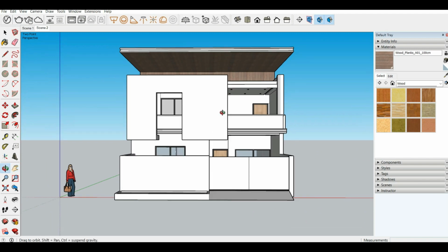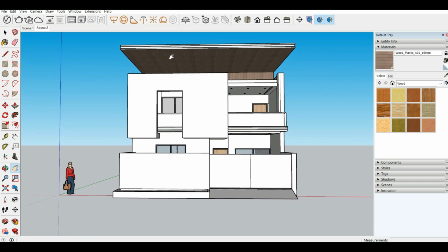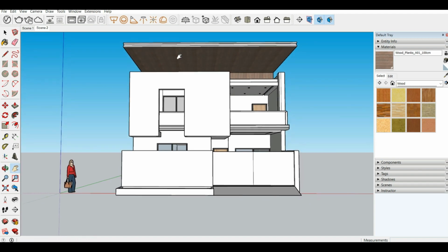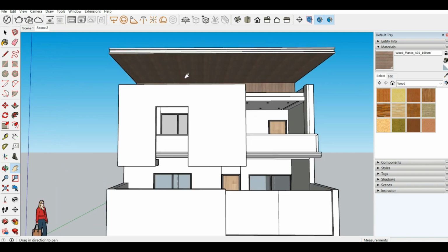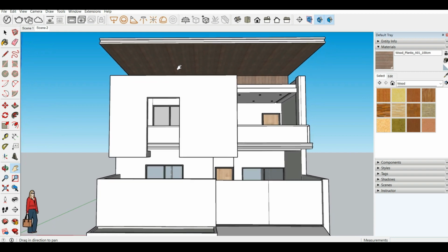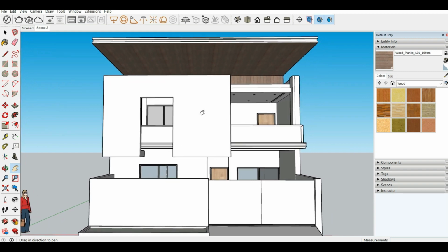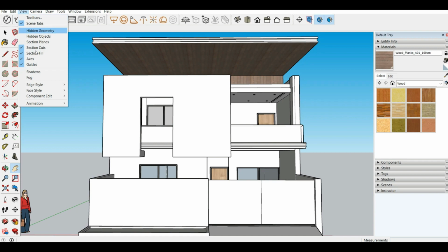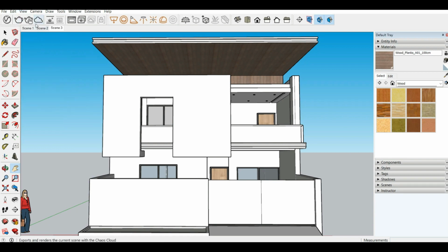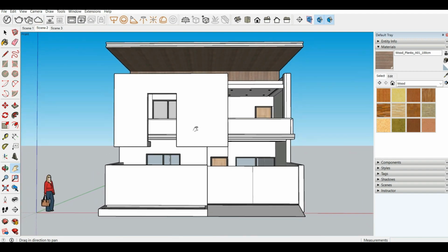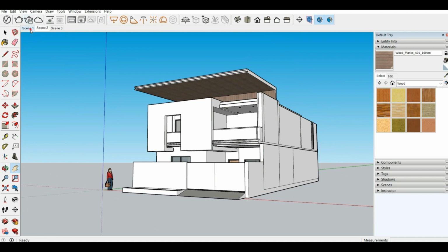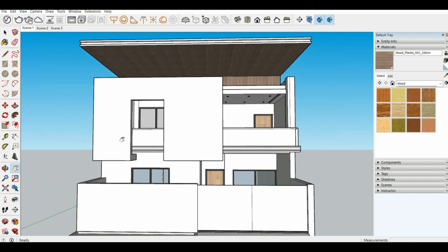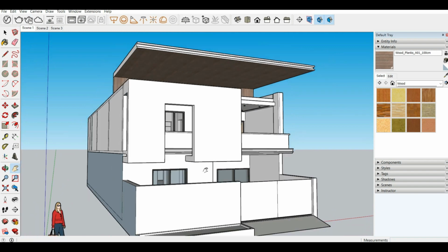So like this you can keep a view you like aside and navigate all you want without having the risk of losing that view, losing that angle. So I'm just going to add another scene. I will just put it in a new view and add another scene. Animation, view, animation, add scene. So I'm doing this again and again so that if someone is working side by side while watching this video, which is recommended by the way, they do it again and again as well and practice it.